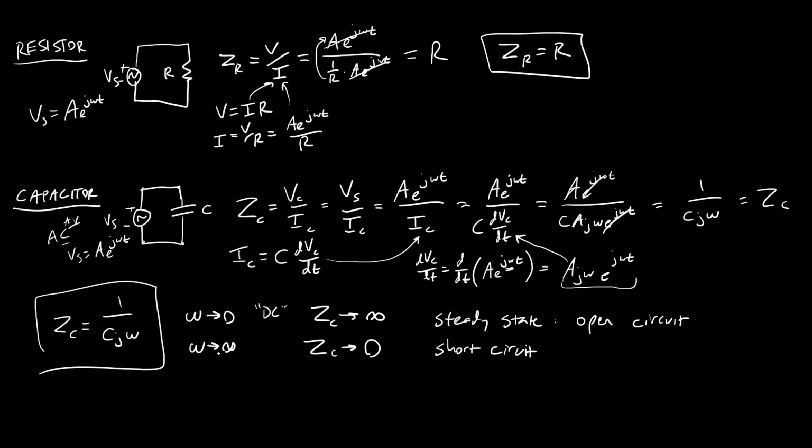And this is going to be interesting when we use capacitors, resistors, and inductors to build filters in future videos. So again, we knew before that in DC steady state a capacitor acts like an open circuit, but now we know that for high frequencies, the capacitor acts like a short circuit. If I can remember how to spell frequencies.